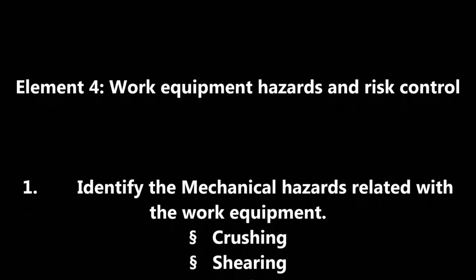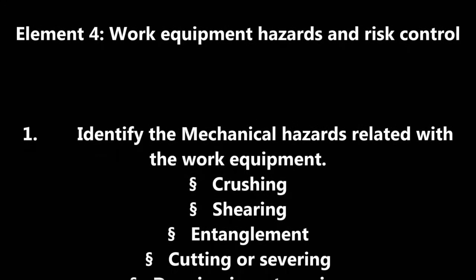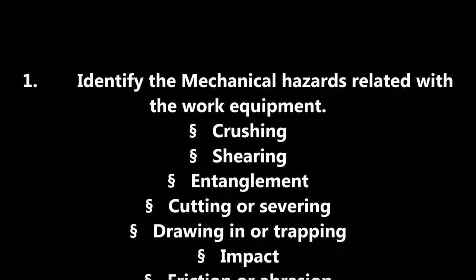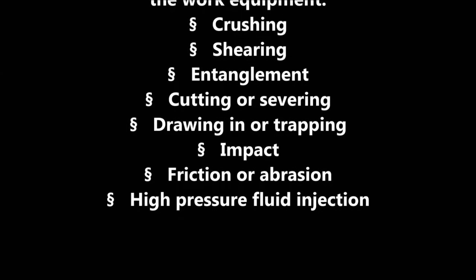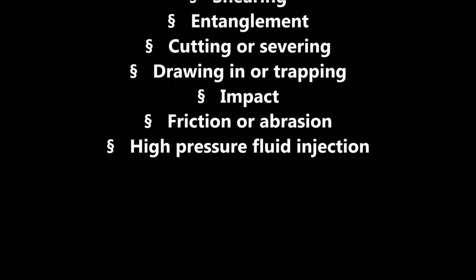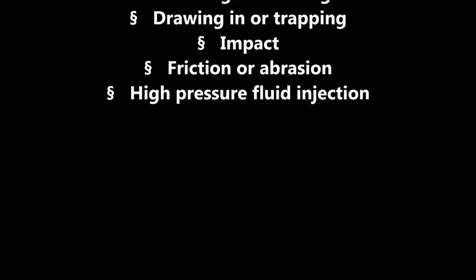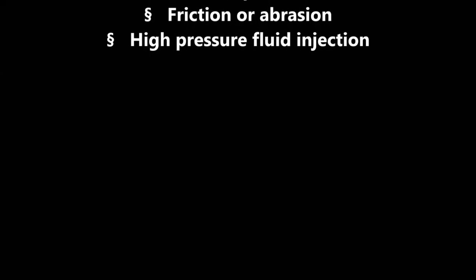Element 4, Work Equipment Hazards and Risk Control. 1. Identify the mechanical hazards related with the work equipment. Crushing, shearing, entanglement, cutting or severing, drawing in or trapping, impact, friction or abrasion, high-pressure fluid injection.